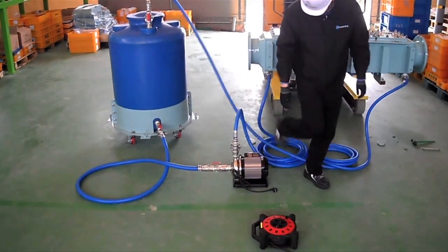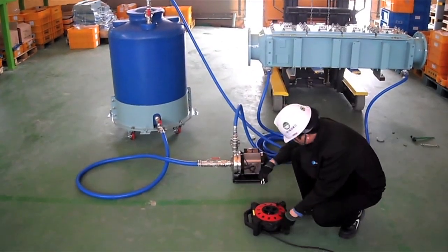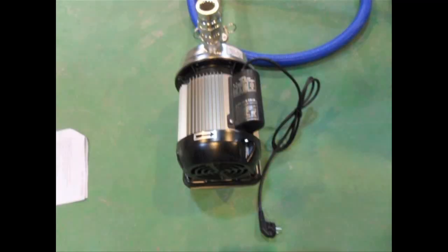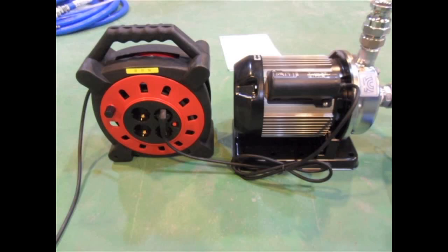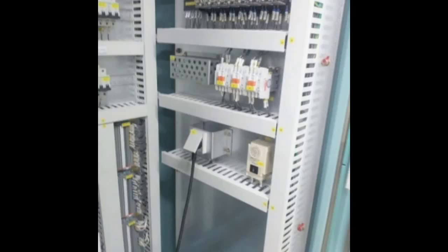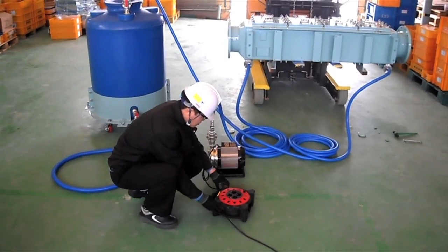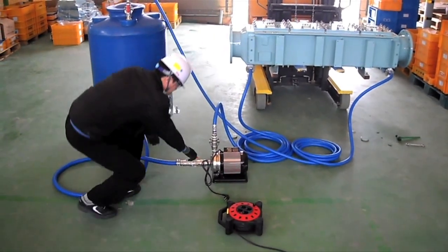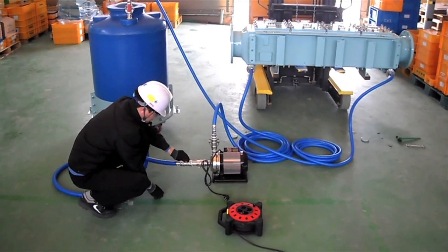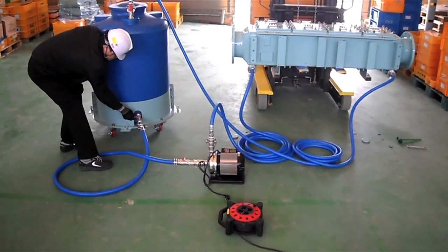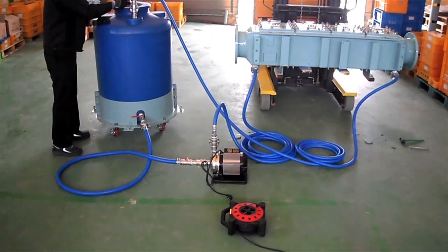9. Open all the valves. 10. Connect power cable 220 VAC to the pump and operate the pump. Pump power can be connected from the receptacle of PDE if power source is not available. 11. Close valves after circulating for 60 minutes. 12. Move on to the next step, collecting cleaning agent and cleaning with fresh water.